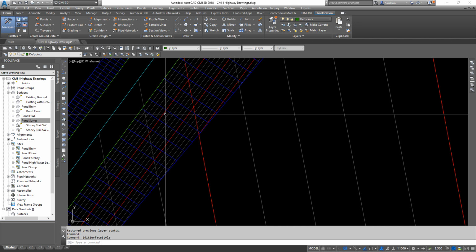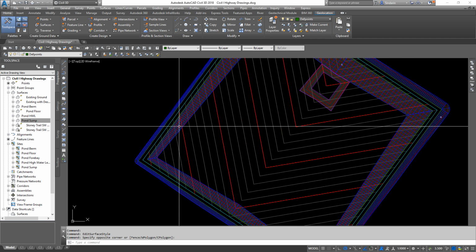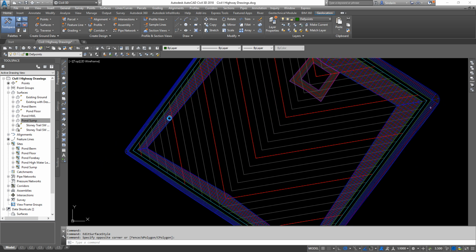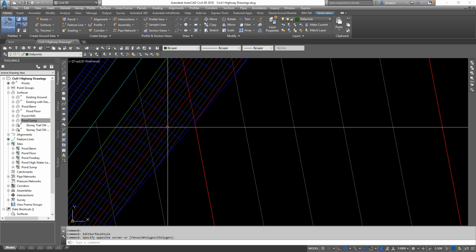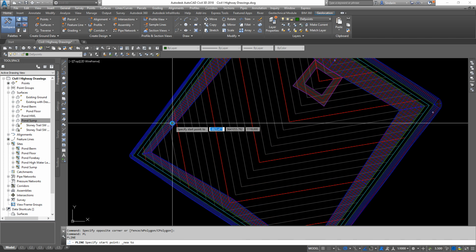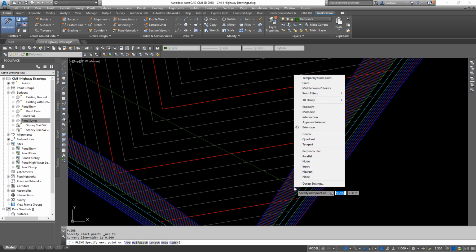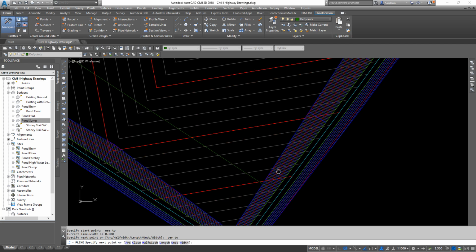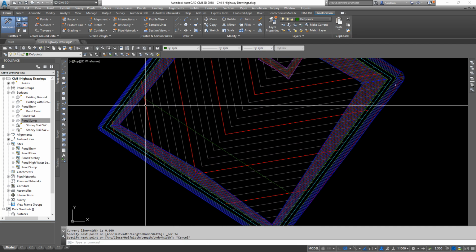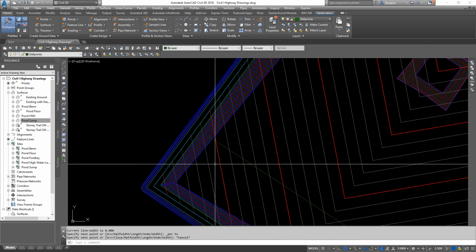Hovering over your berm surface, you can see that this feature line is 1118.009. Now again, part of the pond is not very deep, but that is okay. So I'm going to start by drawing a polyline. I'm going to snap it, and we'll go about 1/3 of the way into the pond, give or take. I'm going to snap it to this 1118. I'm going to go straight across the pond, perpendicular to the 1118 on the other side. So snap it from 1118 on here, all the way across to 1118 on there.